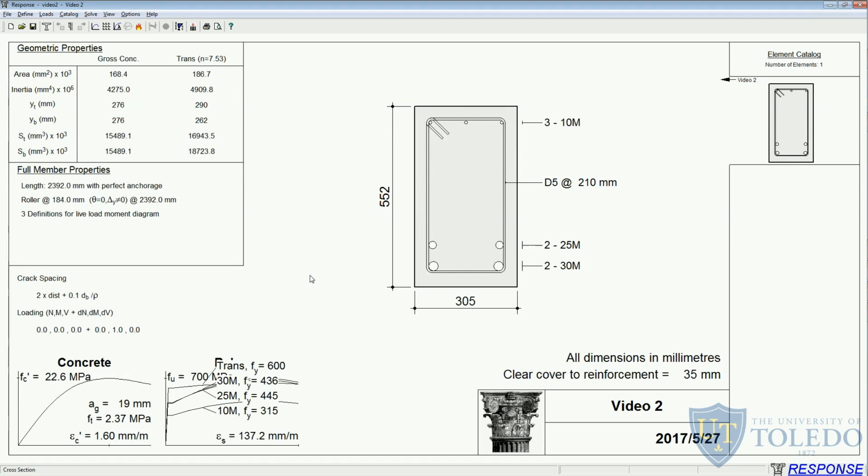Alright, so now we can actually start to get some results we can use in our SAP2000 shear hinge definition. So the first thing we need to do here is to define at which load condition this cross section will be subjected to, because this will be important to calculate both the moment rotation relationship as well as the shear force and shear displacement that this section will be subjected to. Because since this software accounts for the modified compression field theory, both the shear and the moment are considered together and they influence one another based on their relative magnitudes.